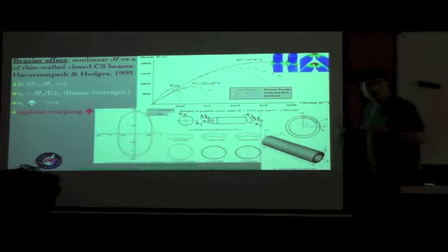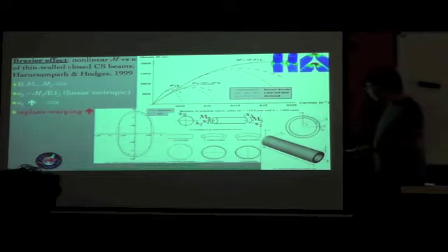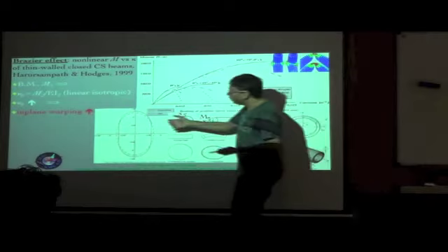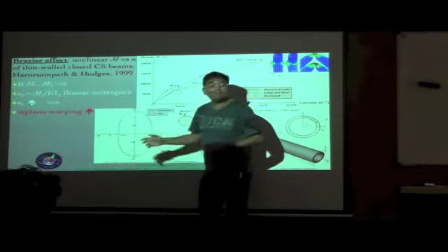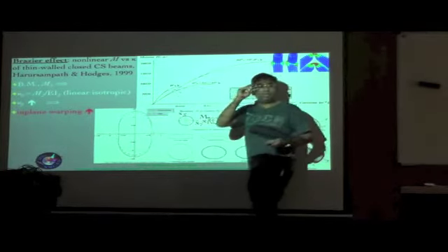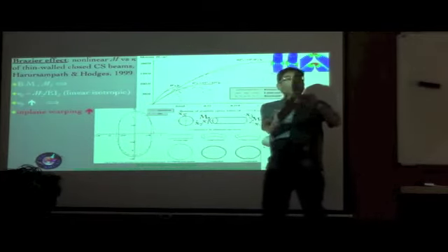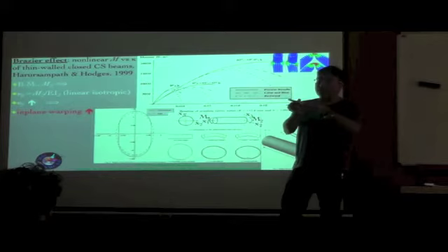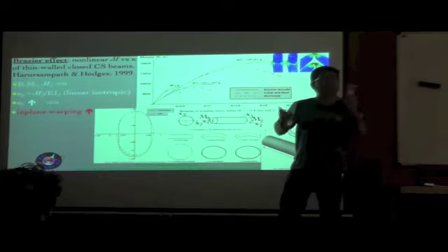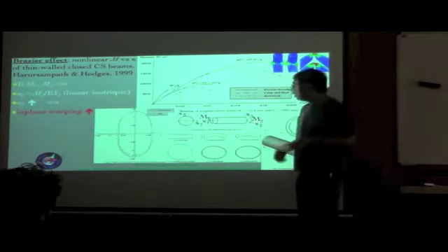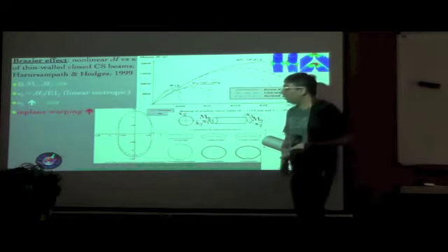That is typically considered by most people, especially when looking at torsion of non-circular cross sections. But what we are looking at here is a classic example of in-plane warping. Another classic example of in-plane warping that we already discussed is when you just have an axial load, and Poisson's effect can be a case where the cross section dimensions change in both directions, and that's again an in-plane warping.